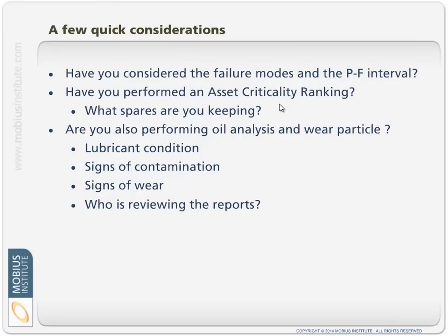Of course, there's a lot more we could talk about in terms of making sure the lubricants are clean, and as part of that we will perform oil analysis to not only make sure that the lubricant condition is correct, but also that it's not contaminated, which can be a very big issue in relation to gearboxes. And then we can look at wear particle analysis to see if there are any signs of wear. You may see signs of wear before you detect it with the vibration readings.